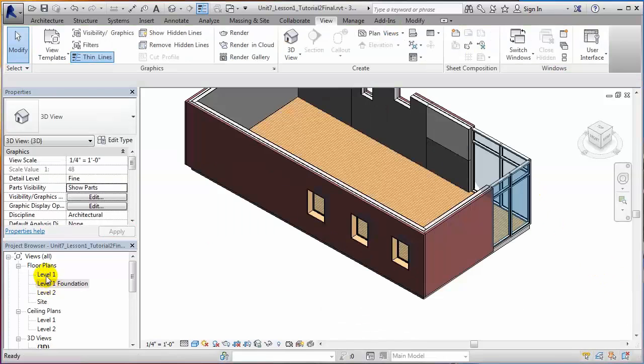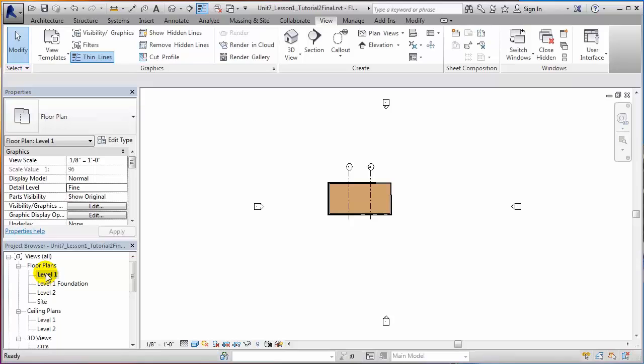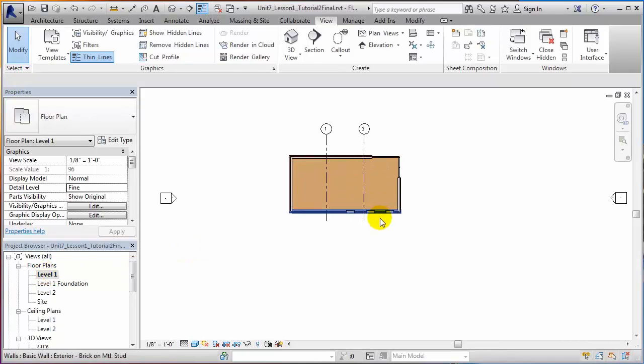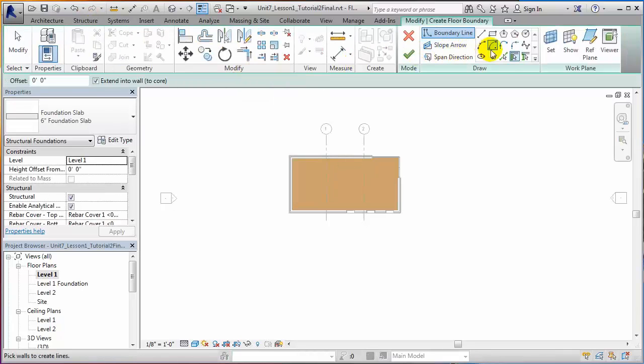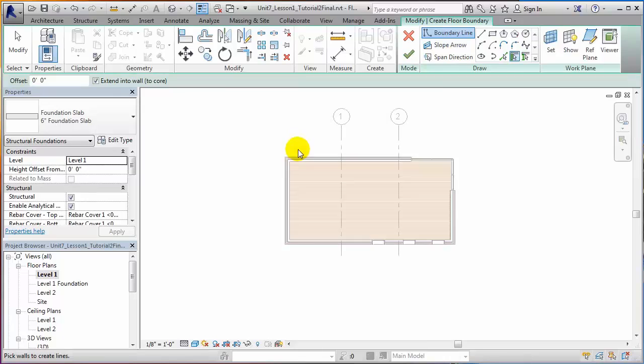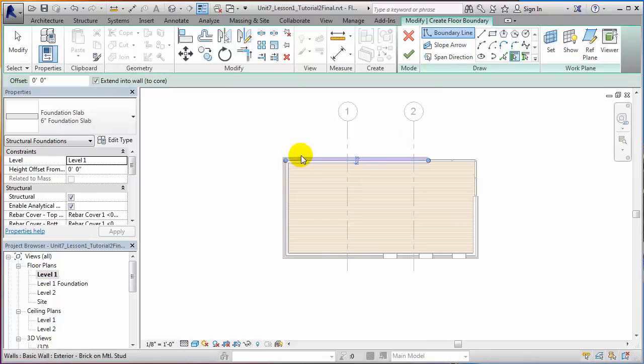Now, returning to the 3D view, let's make one more split to our model in order to reflect a level of detail about material that we cannot see now, this time for the foundation. First, I'll need to quickly model a foundation covering the entire footprint of the building. Because I know that I will have a basement below one part of the model, I know that I'm going to need lightweight concrete in that area. From a level 1 view, I will sketch that slab using pick walls and trimming.